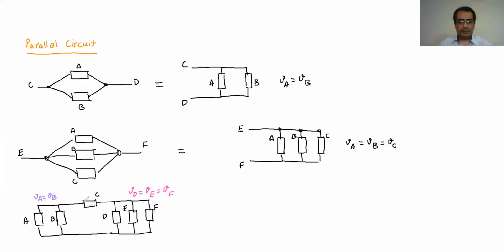other elements, because if you look at C here, one end is connected to A and B, the other end is connected to D and E. So it's not directly connected to any single element, and neither do both ends connect to the same element. So it's neither in series nor parallel to any single element we have here. We have two in parallel here, three in parallel here, and C by itself, which is neither series nor parallel to any of the other elements in the system.